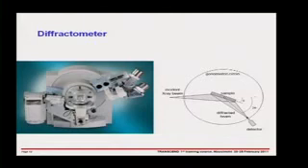So this shows a typical diffractometer. You've got an X-ray generation source here, which fires an X-ray at your sample, and then you've got a detector, which is here, which picks up the signal. This is all automated. Your sample is spinning because you use a powder, but even with a powder, you have a quite low chance of an individual crystal being in a diffracting condition, and you increase that probability of crystals diffracting by having a lot of crystals, as in a powder, and by spinning it round.